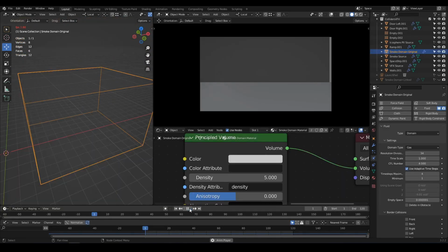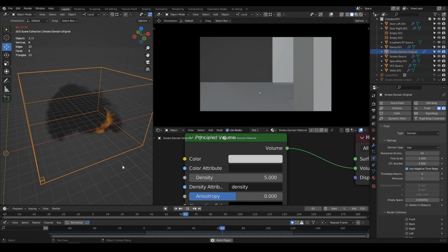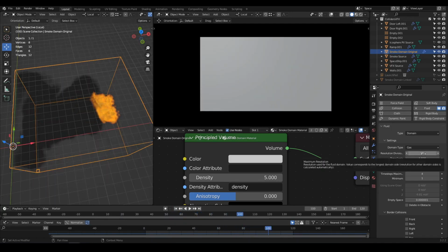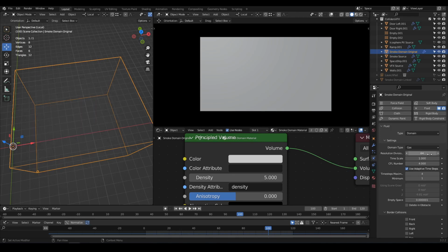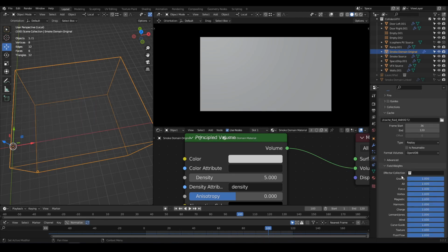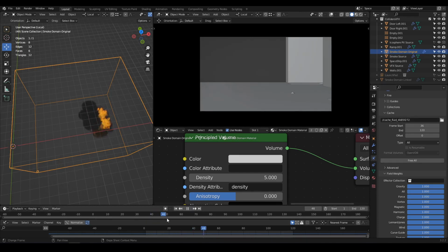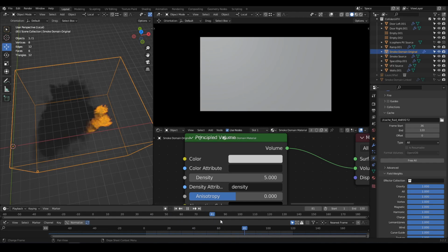and now I'm just calculating the simulation again, which is not too long, because once all the parameters are set, you just have to free the bake and then launch it again. Blender is doing all the rest very efficiently, so I just had to bake it once again without having to worry about the rotation and all the things that we talked about so far.